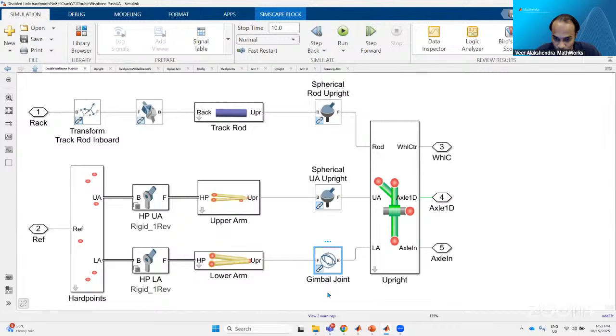It will throw an error that there is a constraint, or in many cases, an error that it has some singularity. So based on your understanding of the theory of mechanisms, you need to use these joints. This is one example of how you model and connect one body to another and define the degrees of freedom.